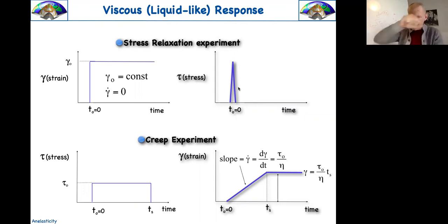If you apply a stress, you take your plate and you move it for a given amount of time, now the strain is increasing. How much? It depends on viscosity. And then it's going to stay if you stop. Here the dislocation, even if it is not the proper word for fluids, the flow has taken time. The fluid is not going back. It's going to stay in the new equilibrium position. How far is it from the initial one? It depends on viscosity.